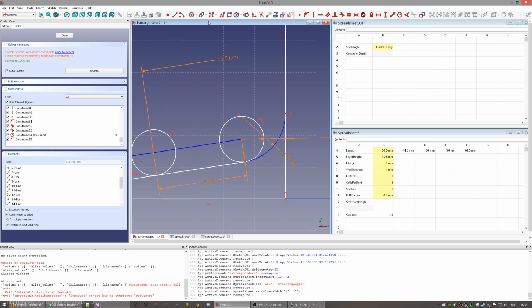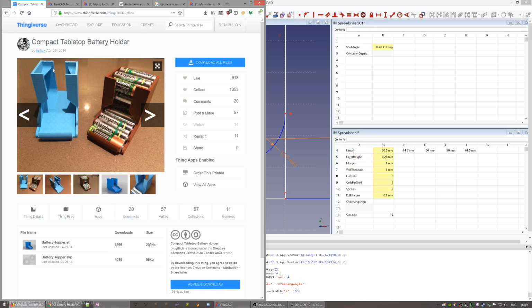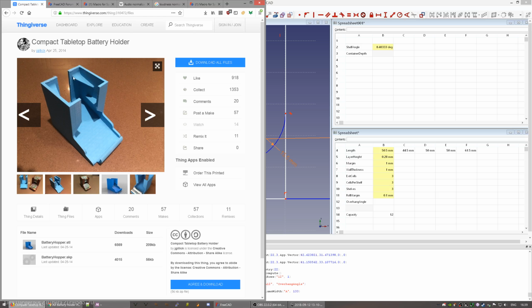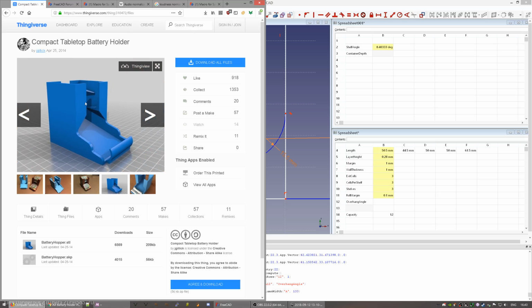Because if they lean too far, there will be nothing to support them, and we will need to add additional supports to print the shape. This design is built to print without support, and that is why you see these angles, for instance. And in particular, that is why this shelf gets narrower as it goes along. And this is quite the desirable feature. The same thing, we can see that the actual profile at the end of the shelf is triangular.